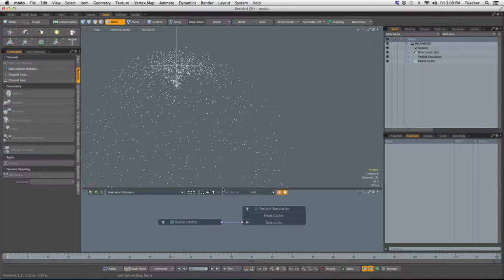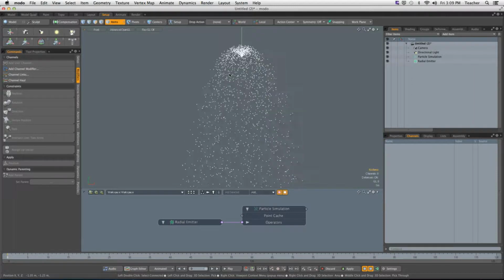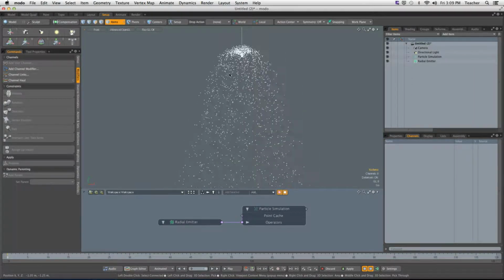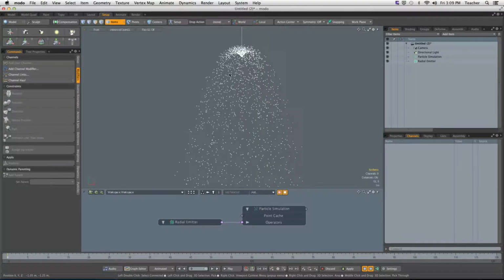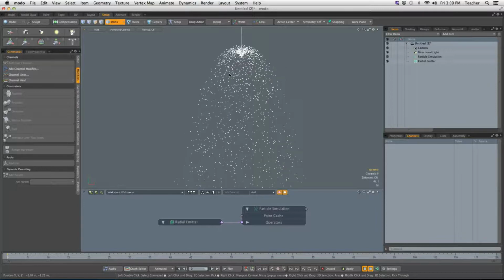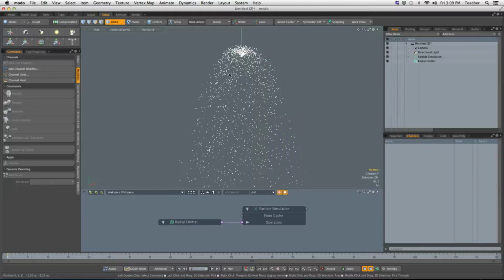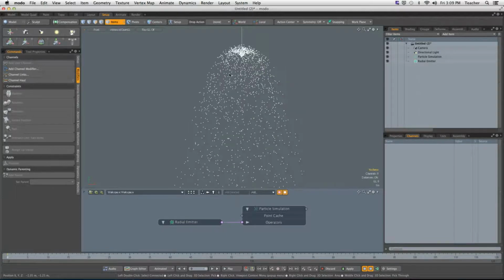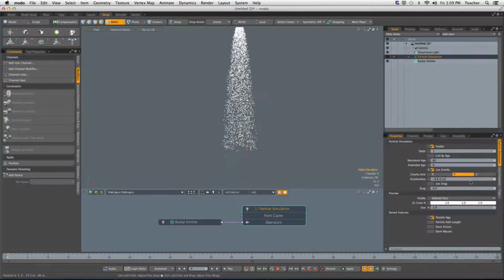Up until now, we've been spending a lot of time talking about how to create particles. Well, I want to control how to terminate particles. I want to kill some particles now, because right now I'm getting my lovely water fountain-y effect here, but they're falling forever. There they are. They're all generally dying down here. The only thing that's determining and controlling when these particles are going to die is the age, the maximum age of 60. This is a when. So after 60 frames, particles are going to start to die.